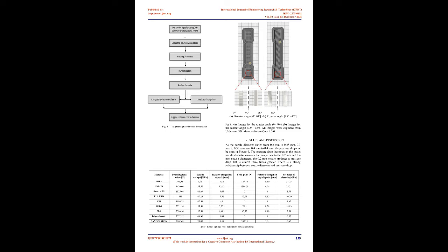To begin, CAD software was used to design a specimen. Stereolithography, .stl, files are exported from the 3D model. They are used to generate 3D models for 3D printing. Creality slicer was used in this research. Before being transferred to the 3D printer machine, it is used to simulate the nozzle movement process. Table 1 gives an overview of the parameters that are set in the 3D printing software. A G-code file is also exported that contains the coordinates for nozzle movements. The 3D printer machine uses it to guide the movement of the nozzle when building a physical 3D object.